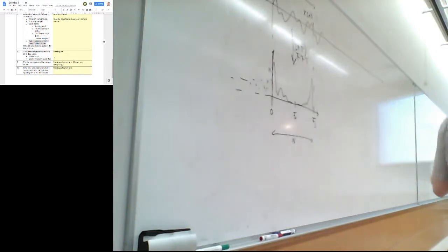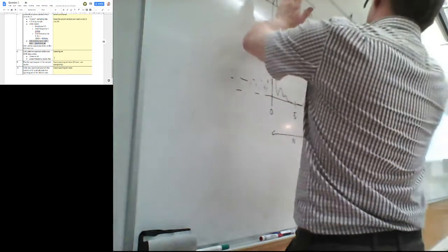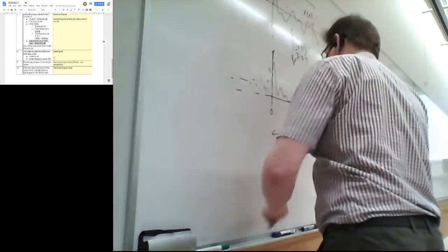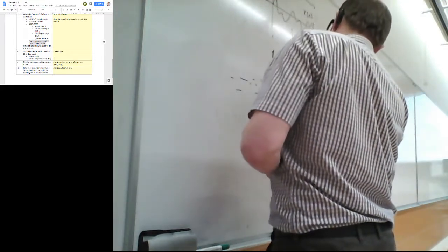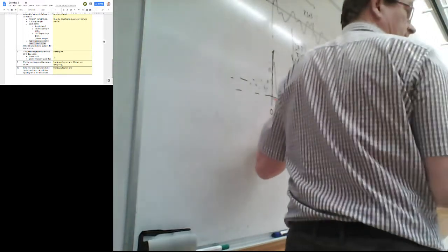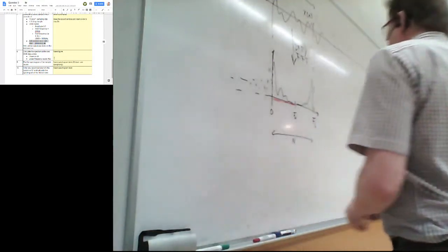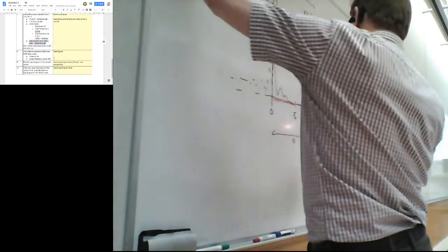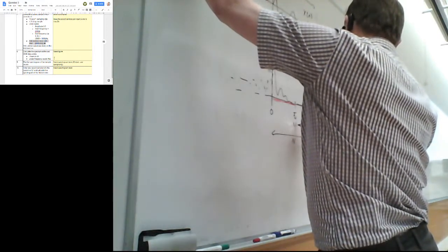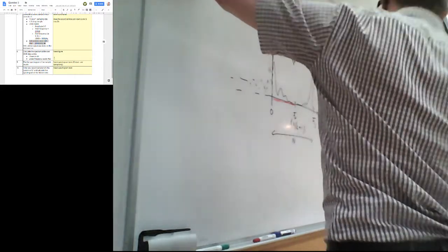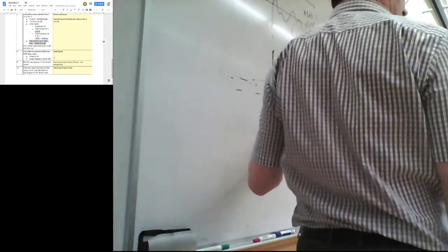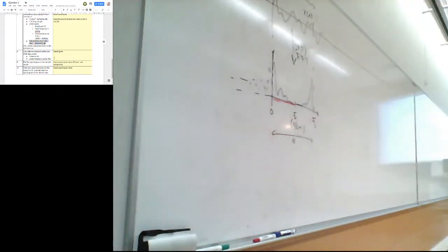Okay, and the fast Fourier transformation maps this into this, and the only part we are interested in is actually this part from 0 to Nyquist frequency. Okay, so basically the index for the middle point is n over 2 plus 1, because this 0 frequency is on the first element. Okay.